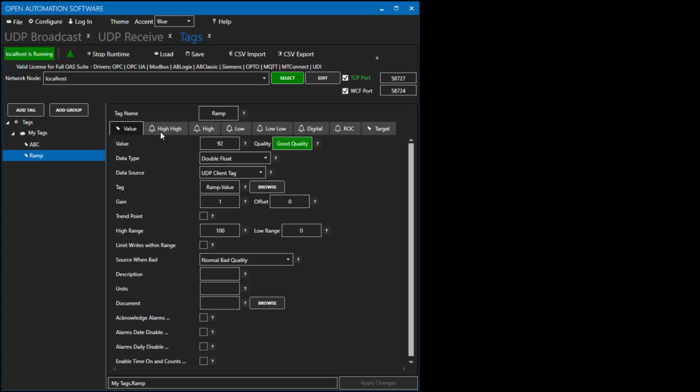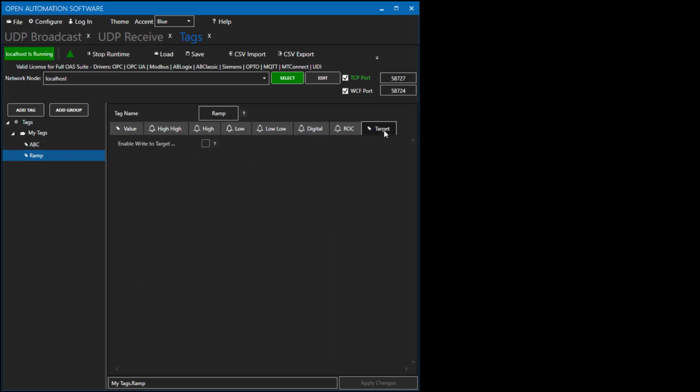If we wanted to transfer the value onto another controller, we'd use the data route feature and enable the target. Here we can set it up to maybe push the data to Azure IoT directly or classic OPC. But if we select tag, MQTT is another, we could send data to an MQTT broker as well. That's pretty cool. But if we set tag, any tag that's defined as a particular data source, if it's written to that particular tag, it will write it on down. So say Modbus, MQTT, Siemens controllers, Allen Bradley controllers, they would all be able to receive the data